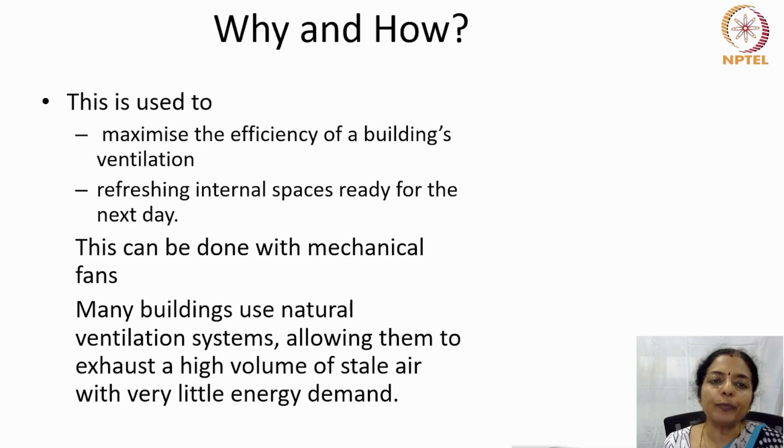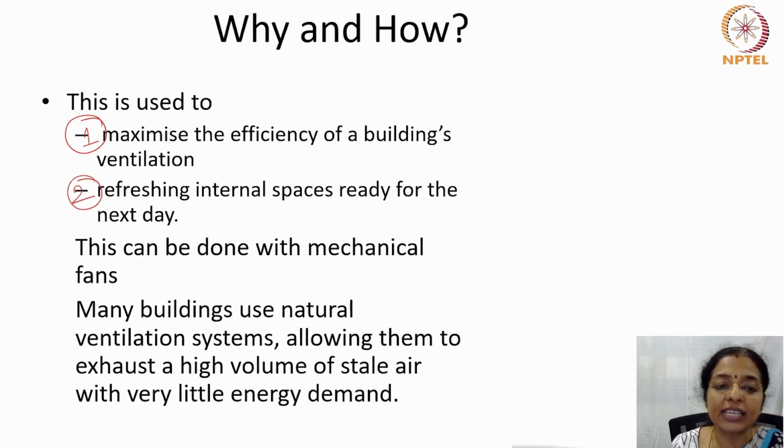So why should we use this and how is it used? This is used to maximize the efficiency of the building's ventilation and to have refreshing internal spaces ready for the next day. This can be done with mechanical fans. Many buildings use natural ventilation systems, allowing them to exhaust the high volume of stale air with very little energy demand.